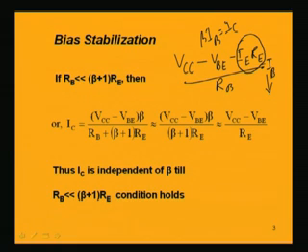So, if IB is brought down, then IC will also be brought down. That means whatever increment of IC has taken place due to the rise in temperature, because of the rise of the saturation current, this effect again brings IB back, because of the drop increased across this resistance, and that again brings down the collector current. So whatever effect was there because of the rise of IC is counterbalanced by this method of self biasing. That is why it is called self biasing. So this scheme is better than the fixed bias scheme in this sense.